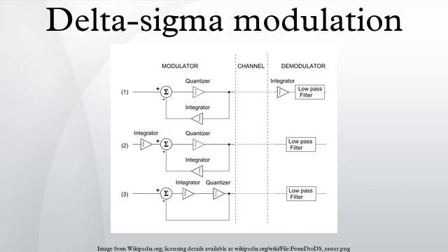Example of decimation: let's have, for instance, an 8-to-1 decimation filter and a 1-bit bitstream. If we have an input stream like 10010110, counting the number of ones, we get 4. Then the decimation result is 4/8 equals 0.5. We can then represent it with a 3-bit number 100, which means half of the largest possible number. In other words, the sample frequency is reduced by a factor of 8,